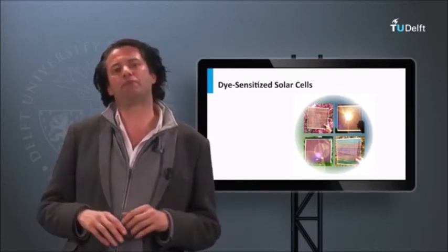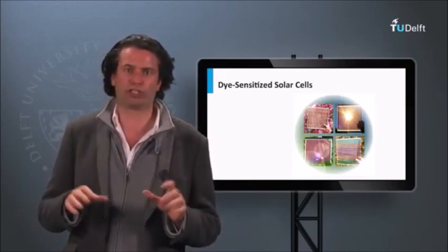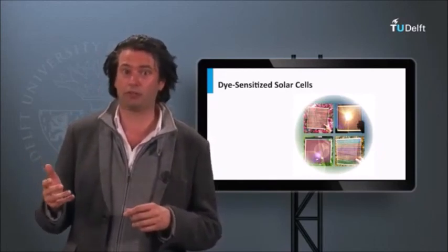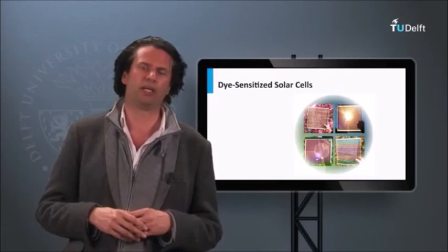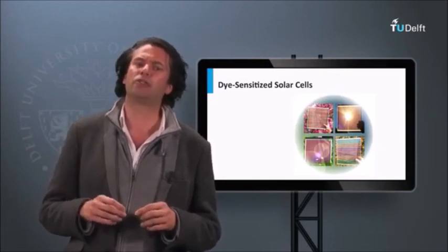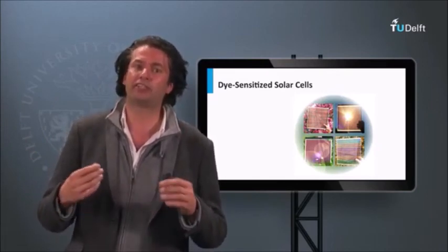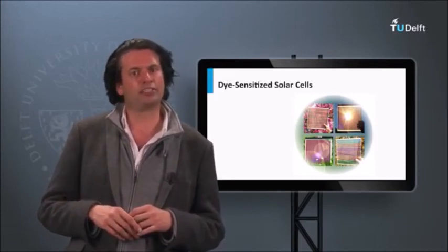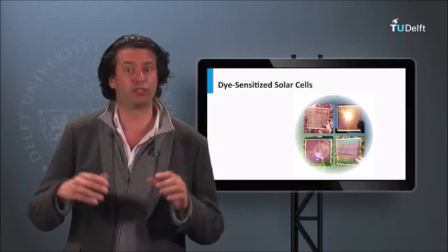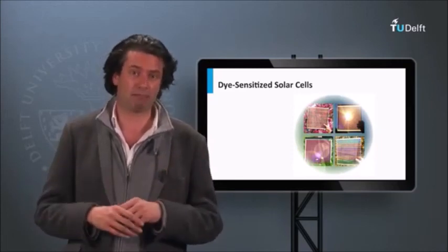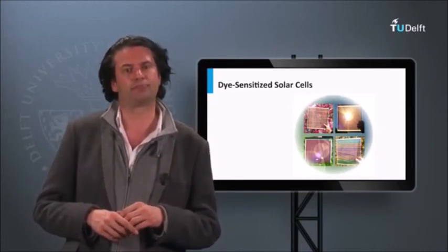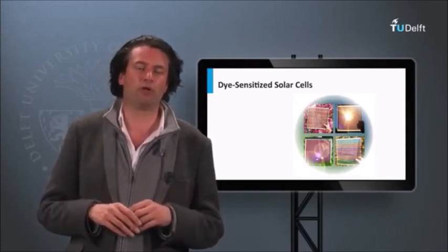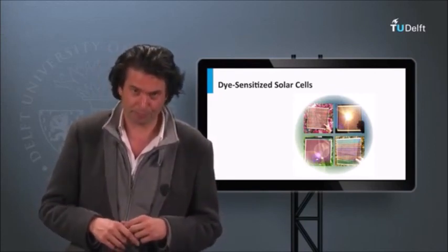The dye-sensitized PV technology is facing some more challenges. One is replacing the expensive platinum electrode material with other cheaper materials. The second one is the development of more stable and resistive electrolyte materials. The third one is the development of improved dyes, improving the spectral and band gap utilization of the solar cells. A dye-sensitized PV product is not yet available on the commercial market.